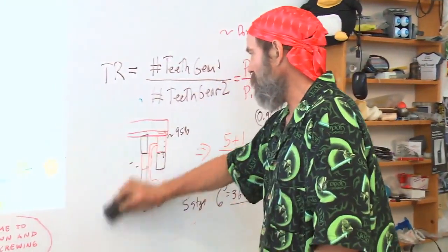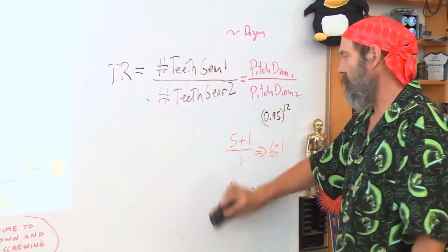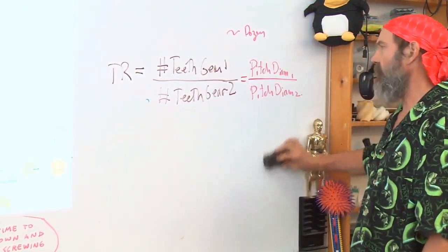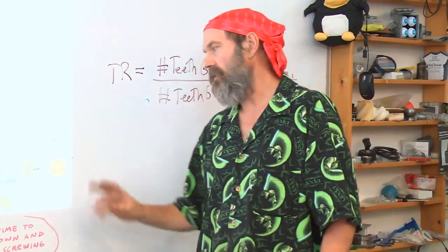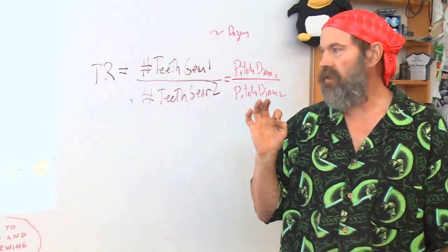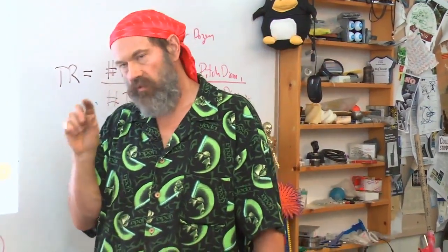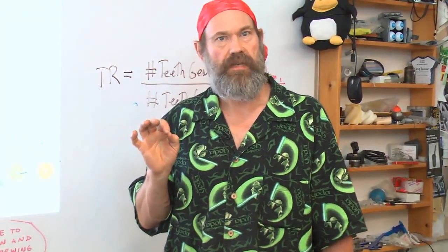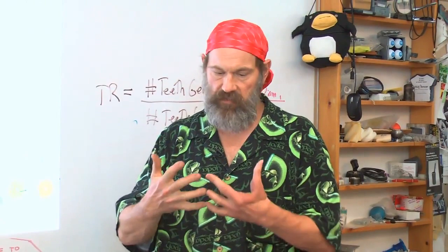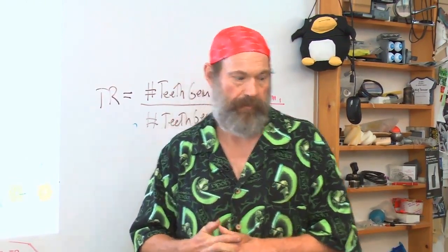But you'll find that most high ratio gearboxes in a small space will use a planetary design, primarily because you get a little bit extra ratio and multiple engagement of teeth at the same time, which you won't get from a normal serial gear train.